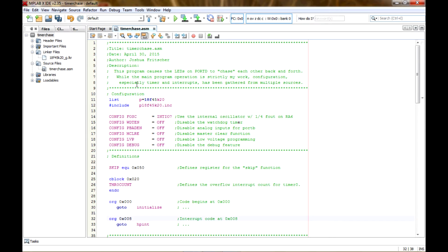So anyway, the first thing I do is configure my oscillator, and what I've done is told it that I want to use the high frequency internal oscillator with IO on RA7. If I put 7.6 here, then it'll give me IOs on RA6 and RA7, but I want to use RA6 as a divide by 4 frequency output.